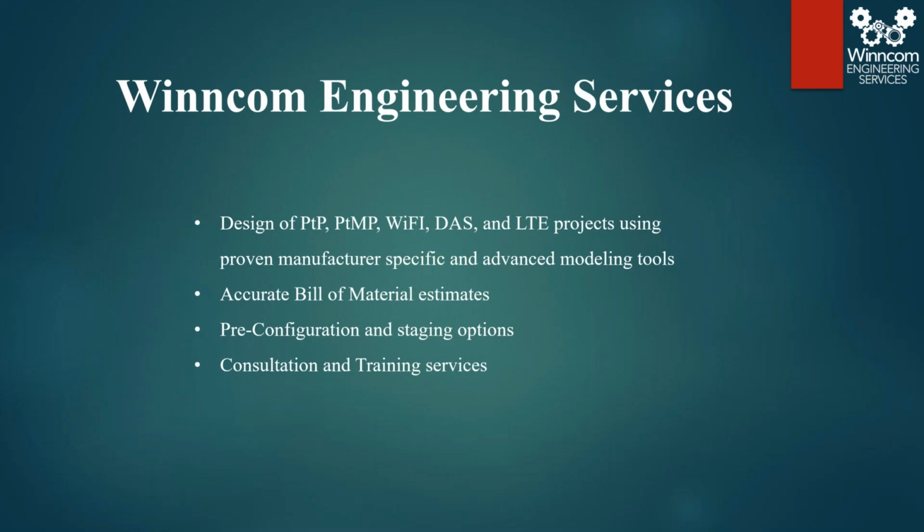So outside of the pre-configuration and staging, we also do design work of point-to-points, point-to-multipoints, Wi-Fi systems, DAS, and LTE projects. We use the best tools out there for LTE propagation studies. We use ATOLL. For Wi-Fi, we use AirMagnet. For point-to-point designs, we're using Path Loss. So we utilize all the most advanced tools out there to give to our customers.